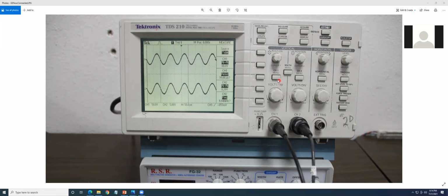Can you zoom a little bit so we can read the knobs properly? I'm asking you, set the channel 1 to AC coupling. Press the channel 1 menu button. Right, exactly. Press the channel 1 button and you select it on the top here, AC coupling.